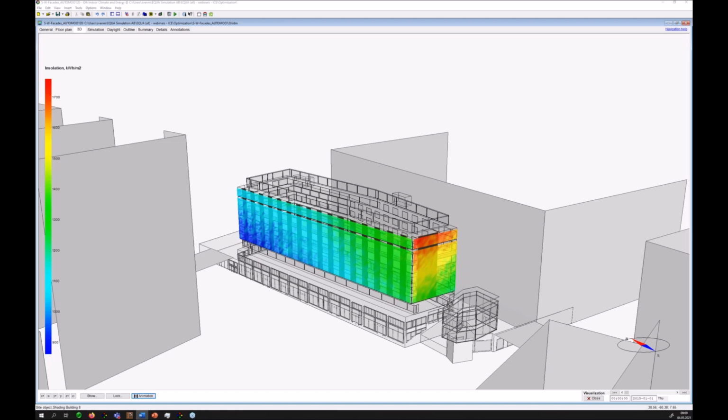After these initial preliminary studies, it was decided that on the longer west facade, the space between the windows should be fitted with PV modules. And on the shorter south facade, the space should be fitted with thermal solar collectors. The heat for heating and domestic hot water will be provided primarily by these solar collectors, of course, and only if necessary by an ambient air heat pump. The main question is in which relation the window areas should be to the module areas here.